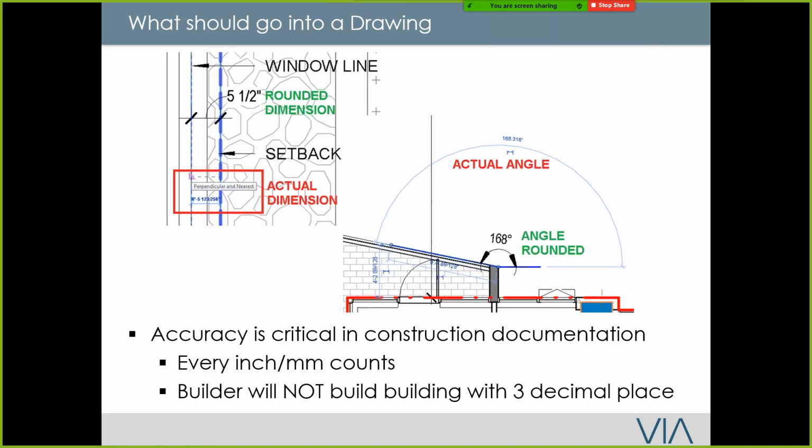All right, accuracy is a big issue in AutoCAD and Revit. So my recommendation is, let's assume you have a setback that measures 5.5 feet. I actually recommend that you do it exactly 5.5, because I've seen people round it off, and what ends up happening is that their buildings are not lined up. It always has this really weird dimensioning.